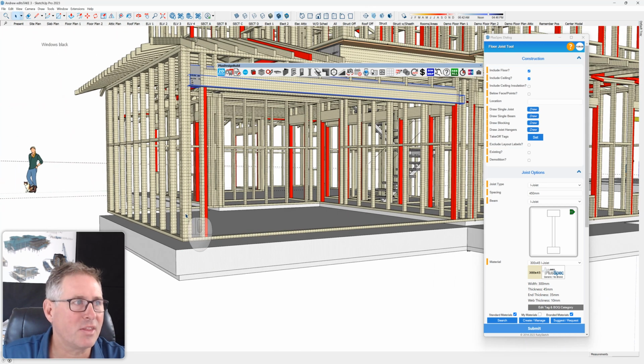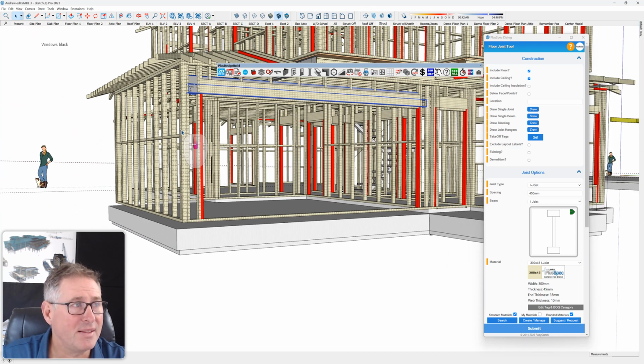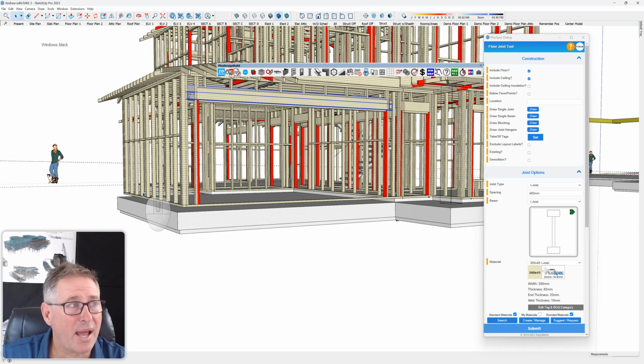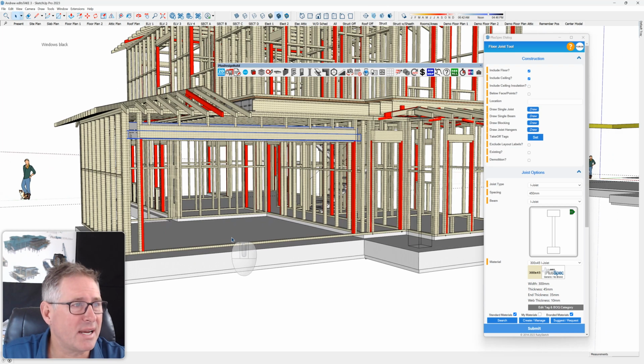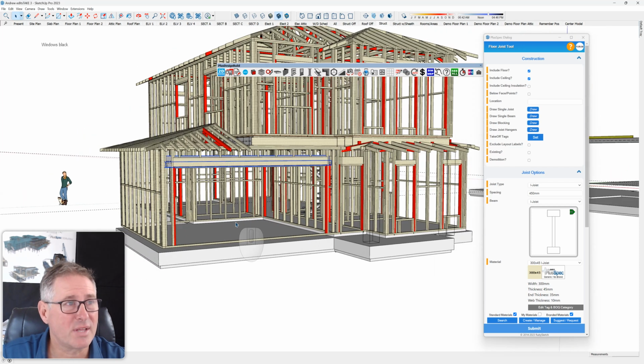So it would have meant that these walls needed to be stepped down and actually made higher. But in this particular case, we don't actually use timber framing in garages. Well, it wasn't my intention. A garage or a set down area is considered a wet area, and therefore putting timber or lumber on the ground can be problematic. So that's why we wouldn't do it technically.